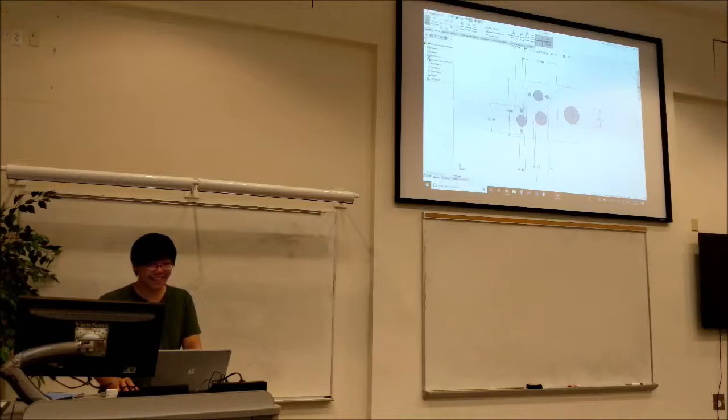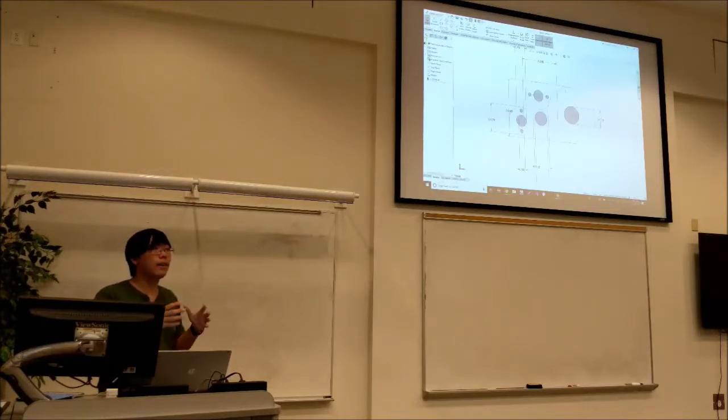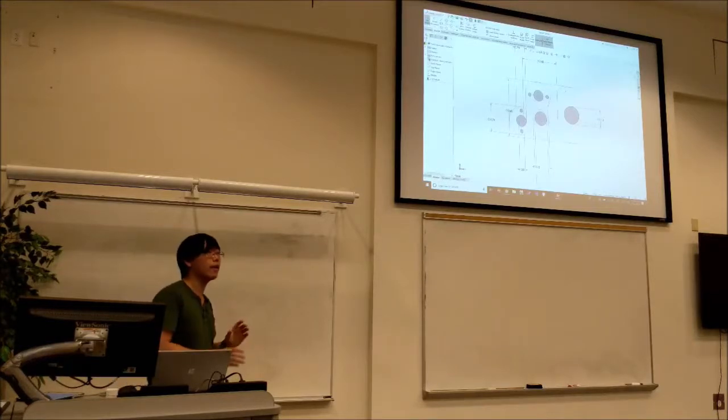But do you guys understand what we're doing, right? So in the sketch, you're modeling the gear as a circle, representing the gear as just a basic circle, and then you can show how the gears mesh together. And when you do that, it'll actually define all the bearing holes for you. Like it'll define where all your bearing holes should be.